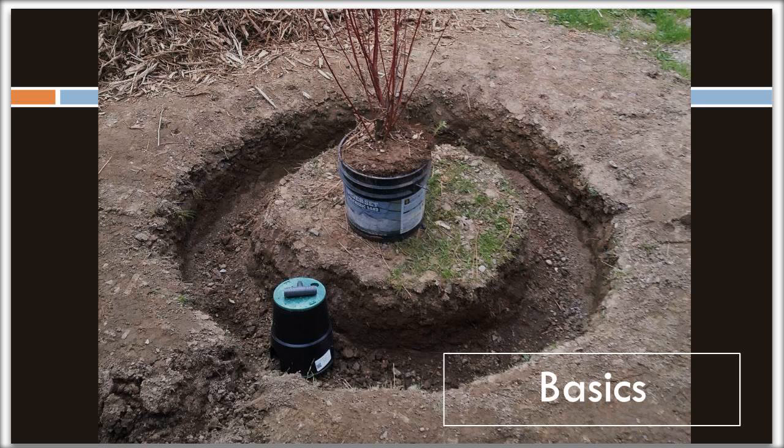Here is the receiving basin for a surge dispersal, and we call it a mulch basin. And you can use a mulch basin even if you don't have a surge capacity. So if you are using a pump-controlled system, there's no reason you can't still use a mulch basin to receive any kind of drip emitter.